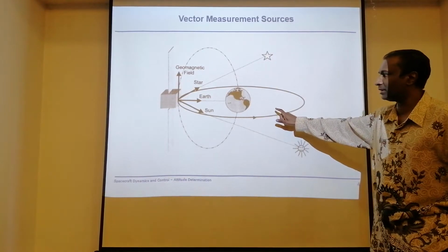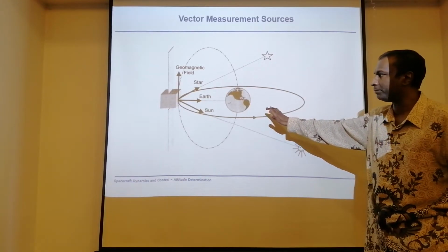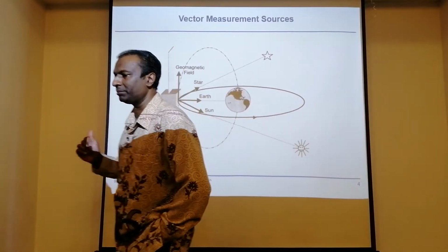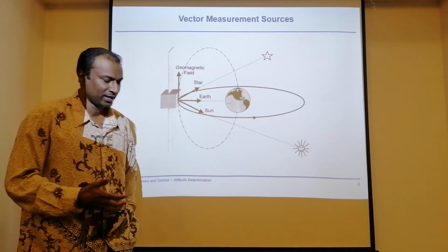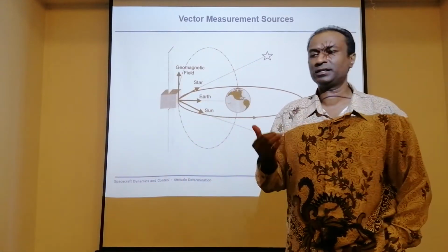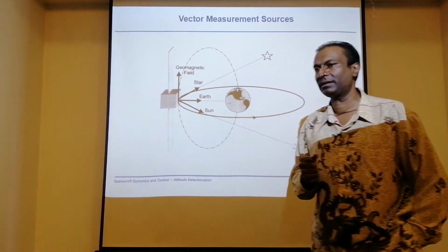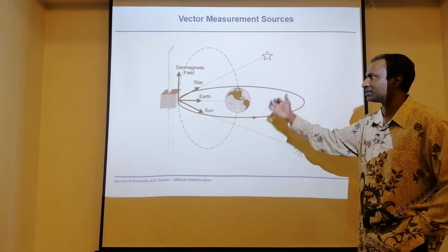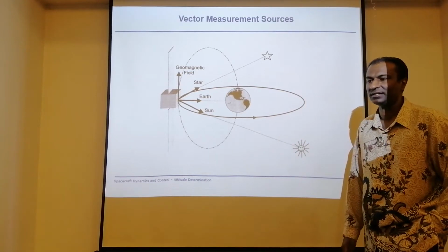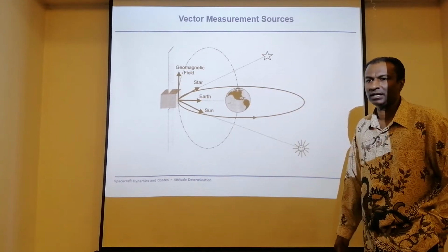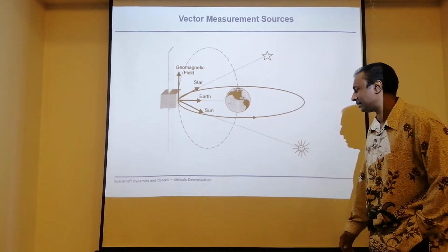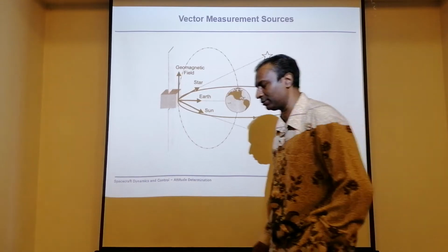We don't put anything related to the gyro here, because the gyro works on attitude rate, so it doesn't depend on an external source for information. That means it doesn't use the sun, a star, the geomagnetic field, or planet Earth. For the gyro, you don't need any external indicators. It detects angular rate, and then from there you do an integration to find the attitude you want.